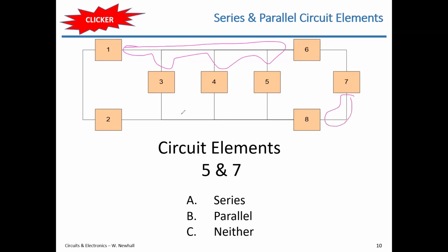So circle the nodes. If I put a circuit element here and then circle the node, I would say this is a node, that blue node, which is completely separate from this green node. So when you define a node, start on the wire, go out until you hit a circuit element, and that's where the node ends. Good question, because sometimes once you visualize this, you can see it, but right before you visualize it, it's not visualizable.